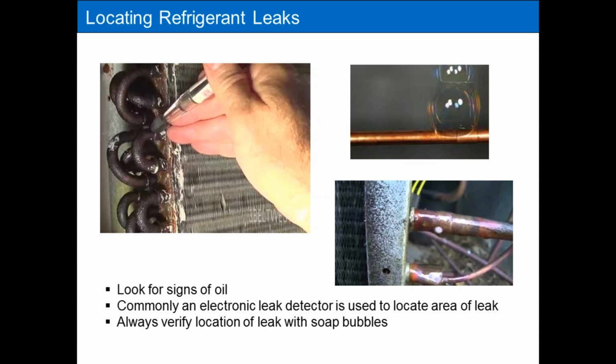If you have a leak in an evaporator coil, best practice, change the coil out. You can try fixing the coils, but you might be chasing your tail. Sometimes you'll fix one leak and then another leak develops. You'll fix another leak and another leak develops. Sometimes it's best just to cut your losses and change out the entire evaporator if you find the leak is in the evaporator. It's not always in the evaporator, but it's pretty common in a lot of these cases.